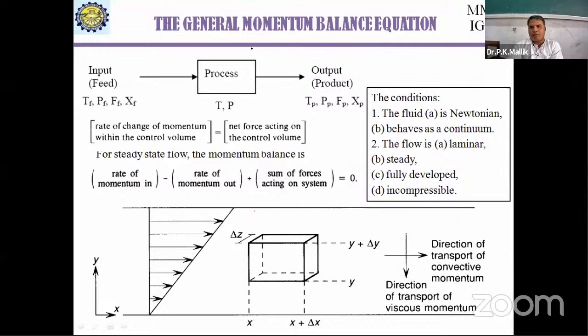Before solving the momentum balance equations, you should first know the fluid properties: whether it is a Newtonian or non-Newtonian fluid, whether the flow is laminar or turbulent, whether it is steady or unsteady, whether it is fully developed, or an incompressible fluid. These are the assumptions you have to consider.